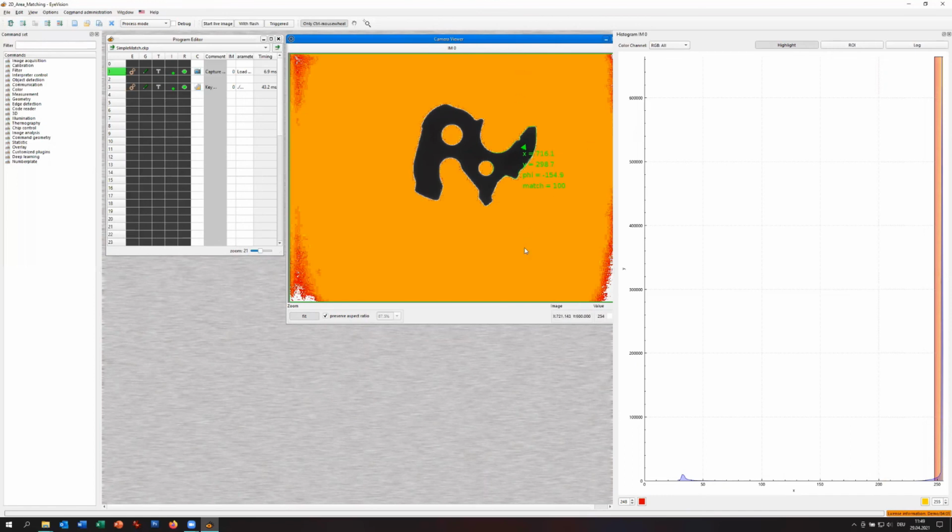That's one of the big advantages of line scan cameras. The other, which really helps, is that you can do a complete shading correction over the line. A shading correction for a camera needs, first of all, a good calibrated basic image and calculation time.